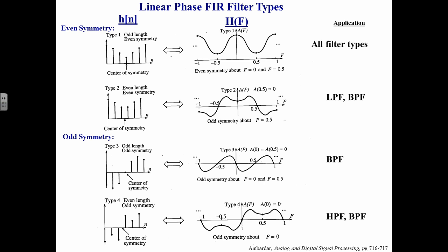And again, we really like this linear phase, this non-distorting characteristic of FIR filters. So a lot of the FIR filters that we'll design in this course and any future courses that you take will generally be these kind that have some kind of symmetry, usually even symmetry, in their unit sample responses. And again, typically we'll shoot for odd length filters that have even symmetry, which will be kind of our gold standard for a linear phase FIR filter.